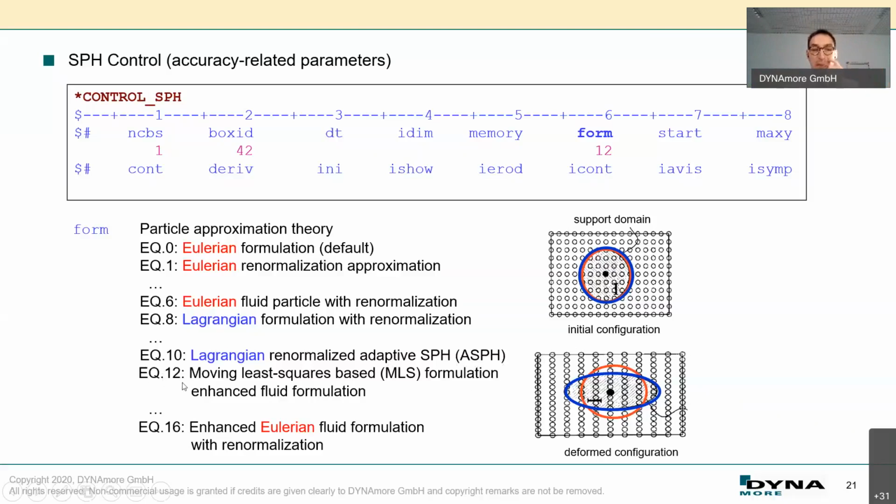Another important one, and quite a recent one, for which I suggest you use the latest version of LS-DYNA, I think R12 right now, is called the moving least square kernel. This kernel does it a little differently. If you recall, I told you the tensile instability is an intrinsic property of the bell-shaped kernel function. So instead of using a Gaussian, bell-like shaped kernel function, it replaces the approximation inside of the support domain by an arbitrary polynomial.